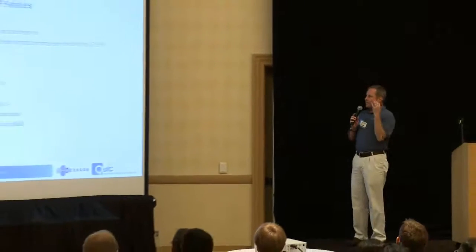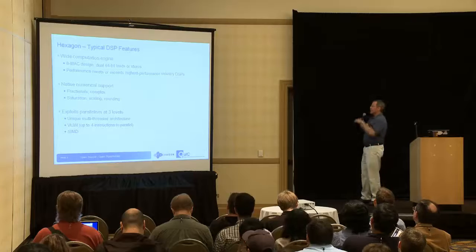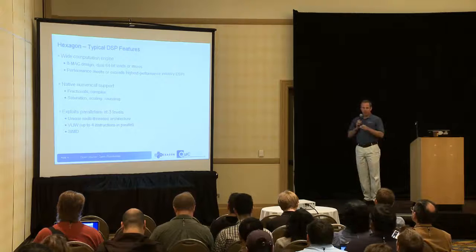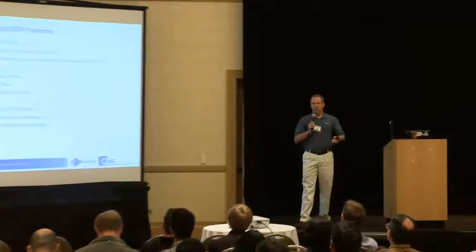It's very general purpose, and we've worked very hard to make it easy to program and to make it very powerful. It's a really high throughput, low energy processor, and I'll talk about some of the ways we get it to be that way. If you want to be a DSP, there are certain things you have to do well. You have to be good at FFTs, dot products, things like that. So some of the first design parameters we had: we wanted a very wide multiply accumulate engine. We have support for dual 64-bit loads and stores. We've always been looking at the competitive DSPs in the industry, making sure that our performance is as good as or better than those.